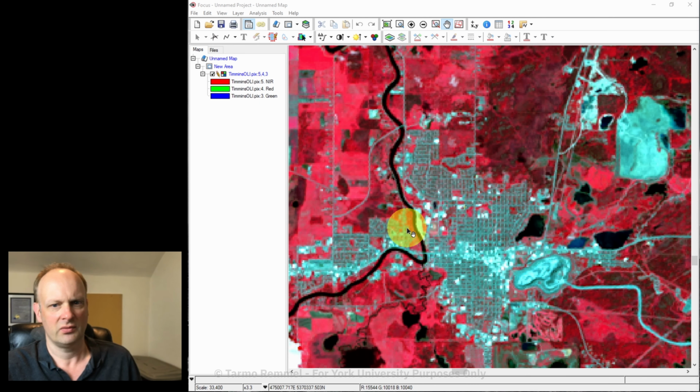and say, well, this is great, but what can I get out of here? How do I know what numbers or values are actually being stored? Where is this location? Very key pieces of information, which we can generally get from the bottom of the screen. So this here gives us an easting and northing in UTM coordinates. This is a projected image. And if I were to click anywhere on this image, notice that it leaves a little yellow crosshairs. At that location, we can read the coordinates off the bottom of the screen.